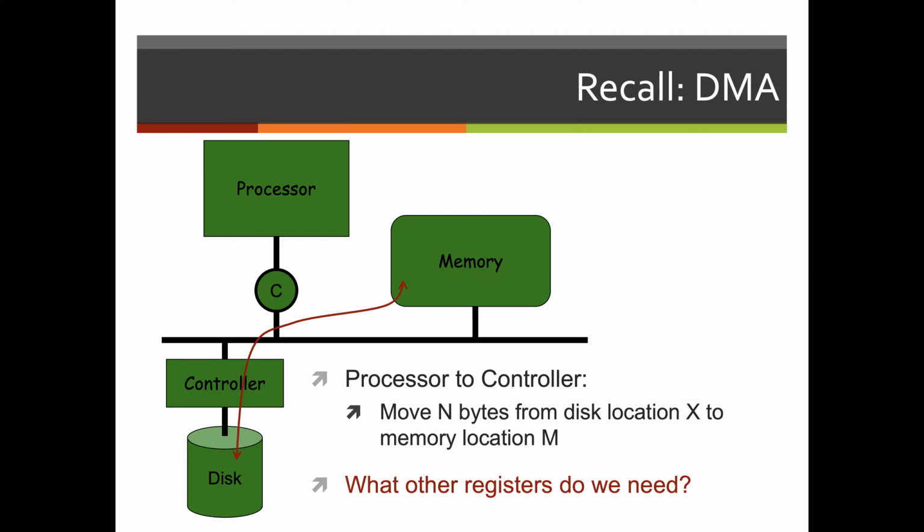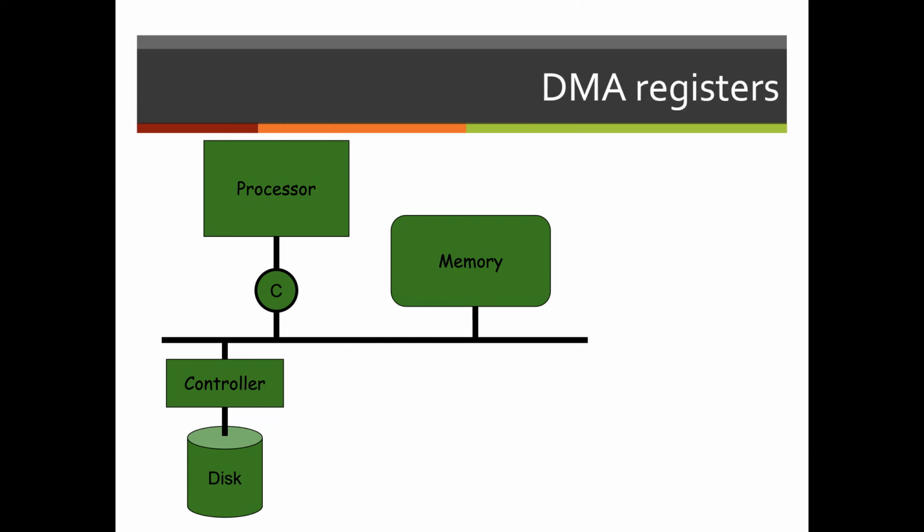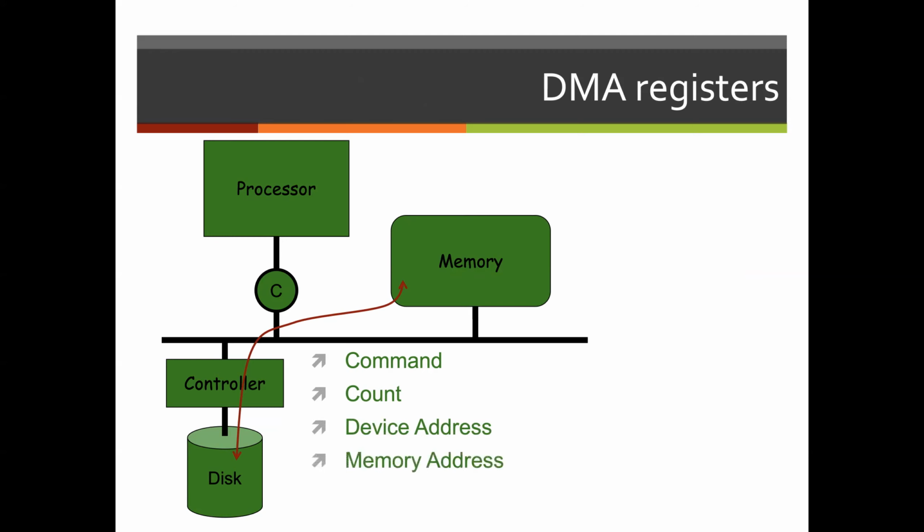And so what other registers might we need? We'll need appropriate registers to store command, count, device address, memory address, as well as status.